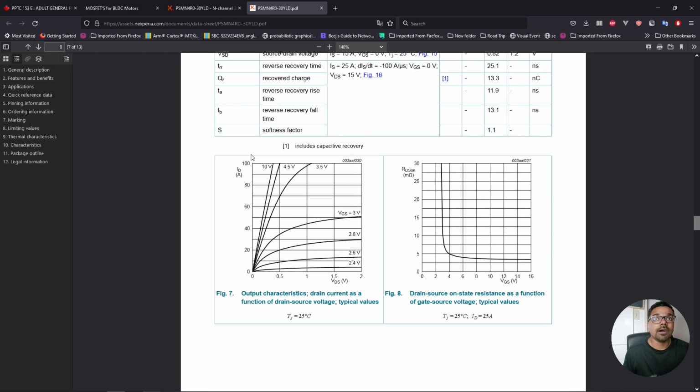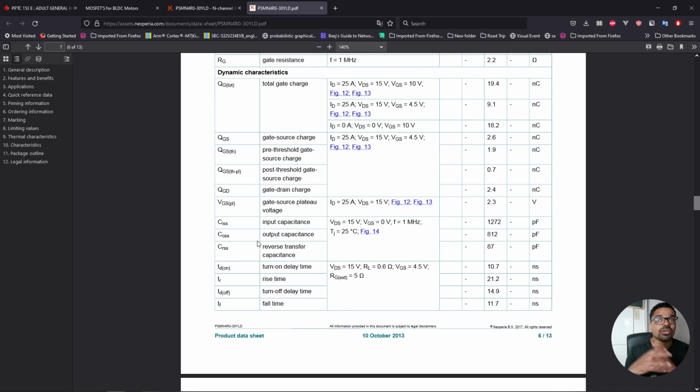And once we understand what these parameters are, we'll try to not just draw the diagram, but we'll also try to make sense of the data sheet. And eventually, if we can get an IBIS model of one of these MOSFETs, we can do some basic simulation to figure out how it behaves when you apply, say, a step response, and the switching characteristics of the MOSFET in simulation.